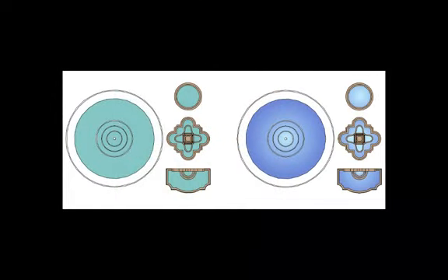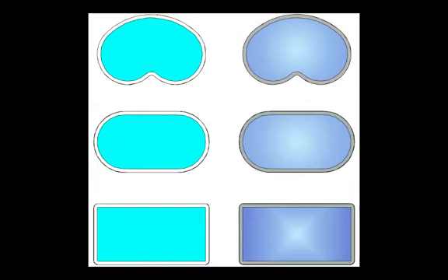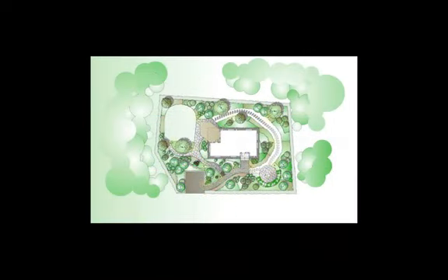One of the more common uses of gradients is to represent a water feature, such as a pool, pond, or fountain. Included in some Vectorworks design series symbol libraries, you'll find some fountains and pool objects that can be easily improved by changing the solid fill in the water areas to a blue or green radial gradient. This is normally a simpler and quicker way of marking out water, as a pattern or a hatch would normally require a legend or key that the observer would have to decode.